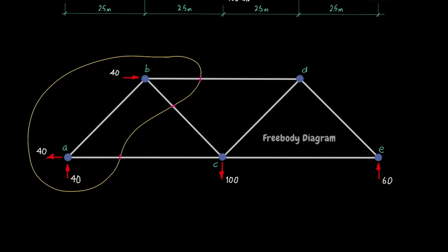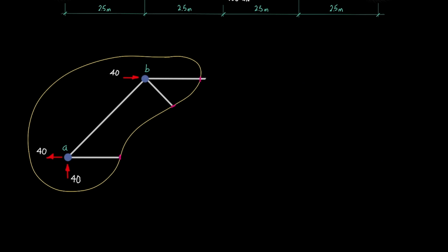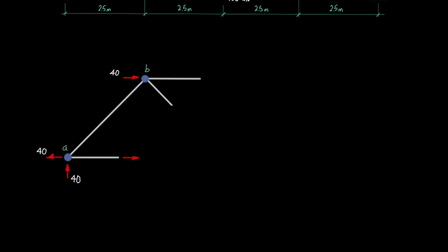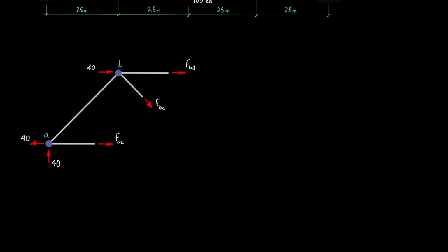Now draw the free body diagram showing everything inside the bubble, including the unknown member forces exposed by the cuts. These forces are always assumed to be tensile. Note, to conserve screen space, the original free body diagram has been modified to leave only the portion of the structure inside the bubble. There are many ways to go about applying the equations of equilibrium to the free body diagram to find the unknown member forces.